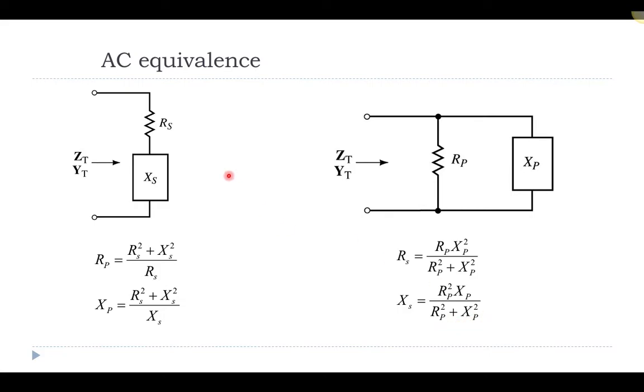If we recall earlier discussions, we can take an equivalent impedance in parallel that has a resistive piece and a reactive piece, and we can convert that into a resistive piece in parallel with a reactive piece. Without going back through the derivations, because we did some of that before, we can determine how these parallel pieces can be found by using the series pieces.